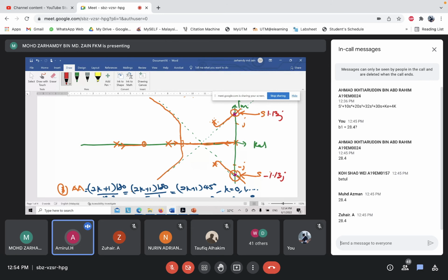Why do we choose 10.6? Because it is critical. Because now, our situation is that once they pass this, it will cross the imaginary axis. So the imaginary axis is the boundary, the critical boundary, where our system can go to the unstable condition and also can go to the stable condition. So from here we can assume this imaginary axis is the critical point.